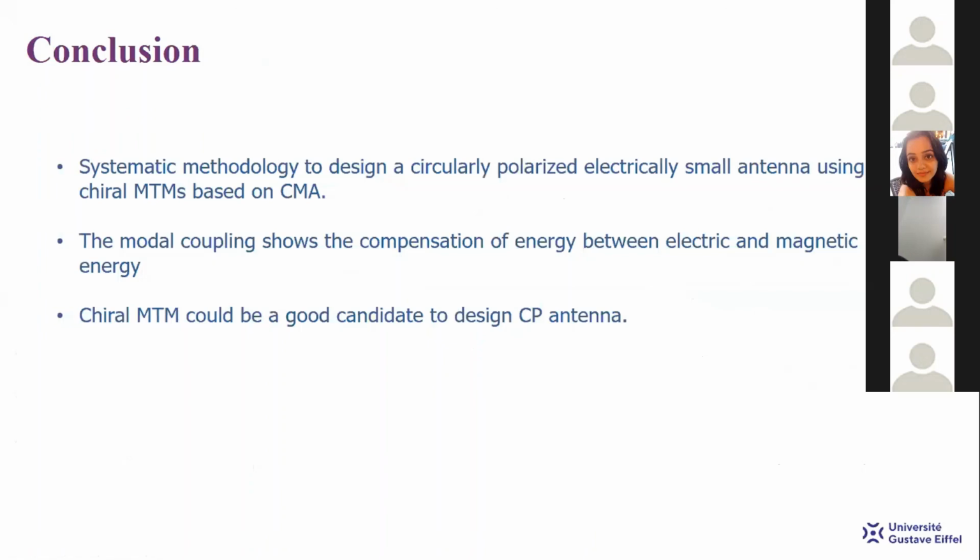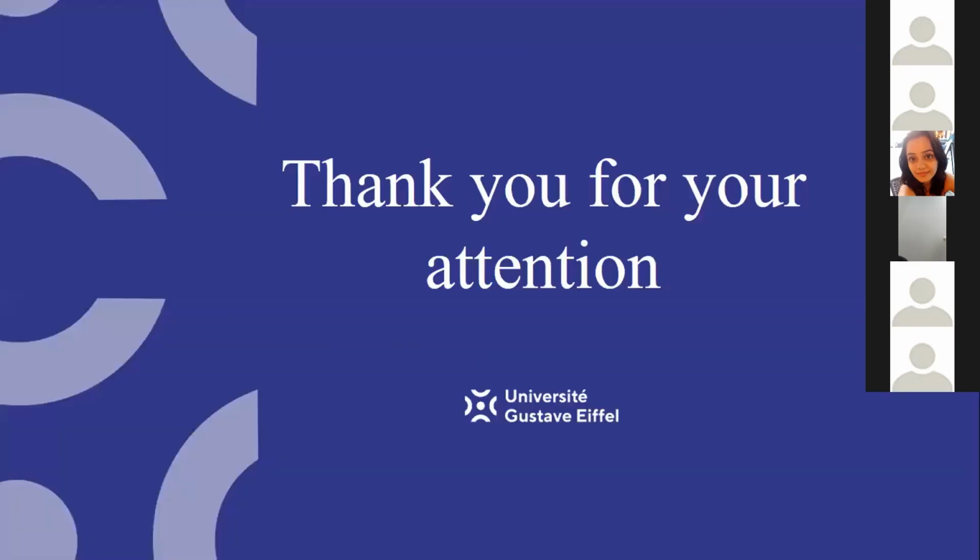As a conclusion, this contribution proposes a systematic methodology to design a circular polarization antenna using chiral metamaterial, based on CMA, by studying the modal significance coefficient and by also studying separately the dipole and the chiral metamaterial. Using the intermodal coupling, we can show that there is an energy compensation between the electric and magnetic energy, and the chiral metamaterial could be a good candidate to design CP antennas. Thank you for your attention.